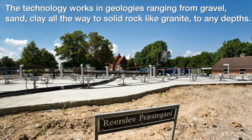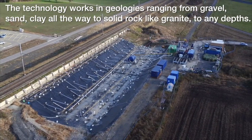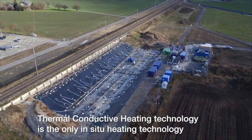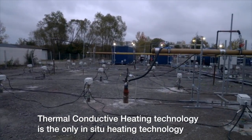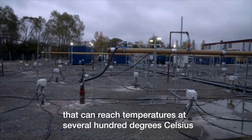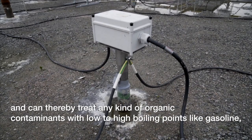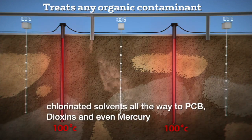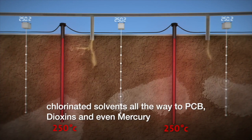The technology works in geologies ranging from gravel, sand, clay, all the way to solid rock like granite to any depths. Thermal conductive heating technology is the only in-situ heating technology that can reach temperatures at several hundred degrees Celsius and can thereby treat any kind of organic contaminants with low to high boiling points like gasoline, chlorinated solvents, all the way to PCB, dioxins and even mercury.